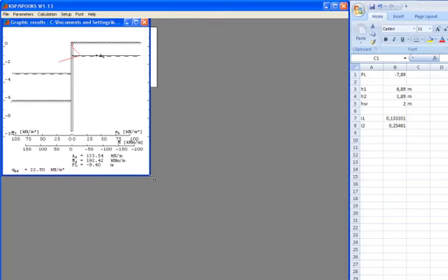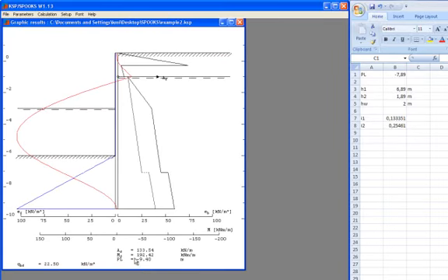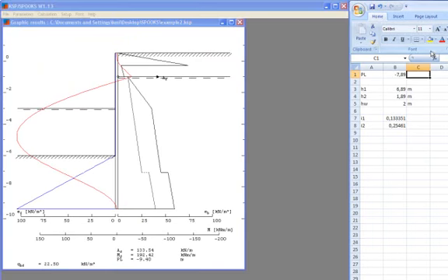The results show that we have a significantly larger driving depth here, which will again change the gradients on the wall. So we need to calculate the gradients once again. We need to enter over in the Excel spreadsheet a new value for the driving depth. It's now calculated to -9.4.